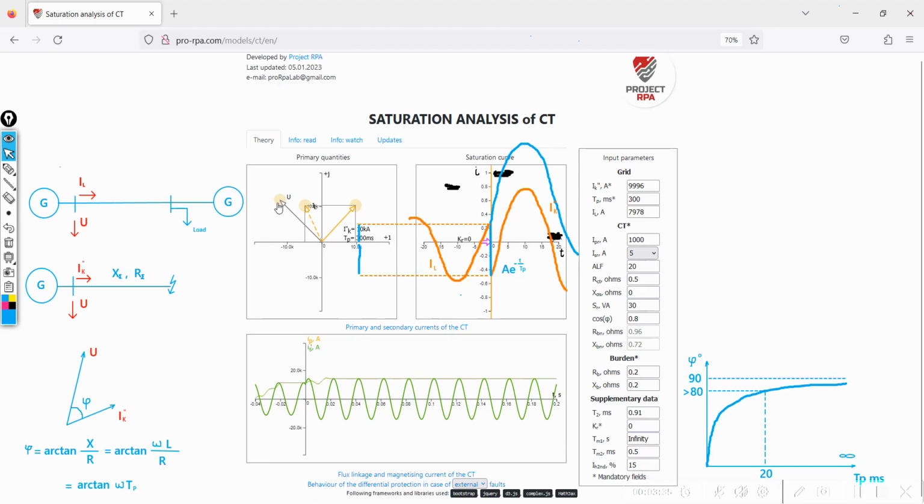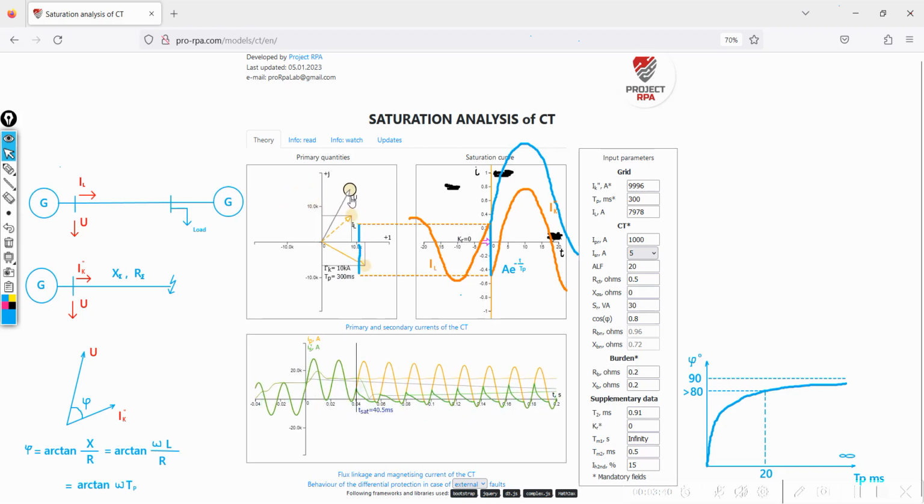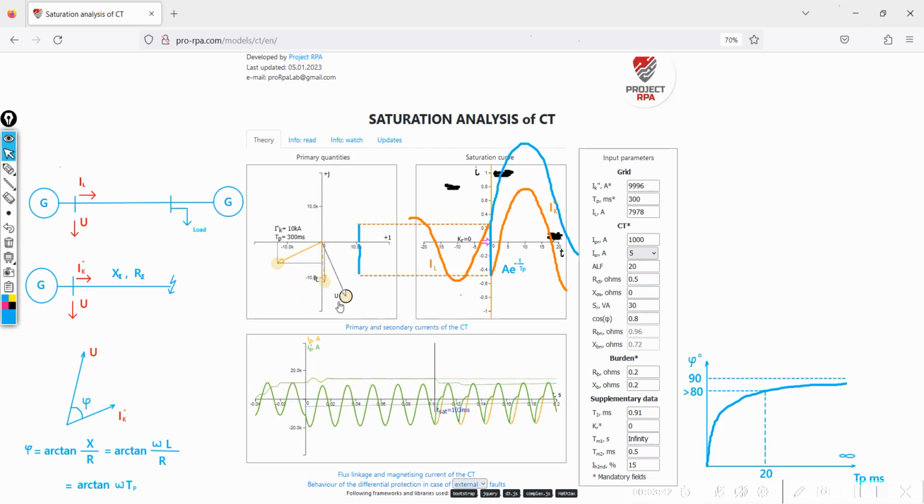An important point that needs to be addressed is that the voltage phasor is not subject to any change in scale because it is, so to speak, only an auxiliary phasor, which is only there to change the fault inception angle.